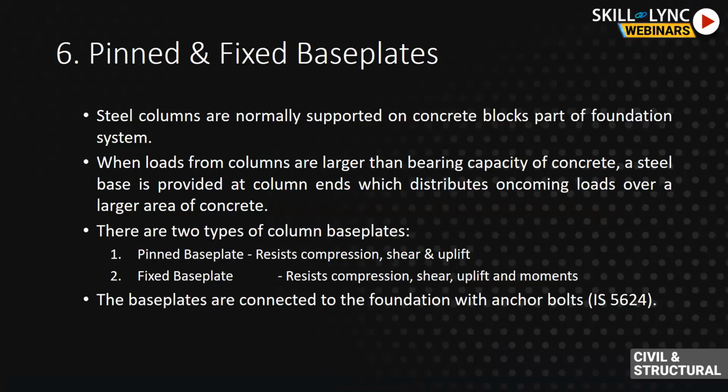The base plates are connected to the foundation with the anchor bolts. And please note that the anchor bolts are different from the connection bolts which we saw in the shear and the moment connection. The connection bolts for the shear and moment connection would be 8.8 grade, while the anchor bolts which are generally used are of 4.6 grade. The IS code which will give you more information about the anchor bolts is IS 5624.